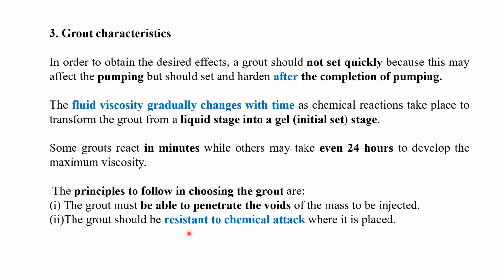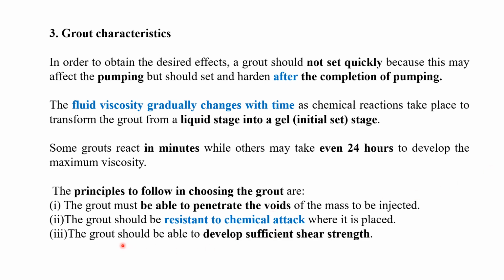The grout should be resistant to chemical attack. That means chemical attacks should not be there once you are going for the grouting. It should penetrate easily, right? The grout should be able to develop sufficient shear strength. So while choosing the grout, we have to consider these parameters, or we can say the grout should have all these three characteristics.